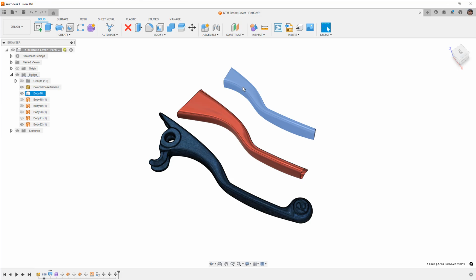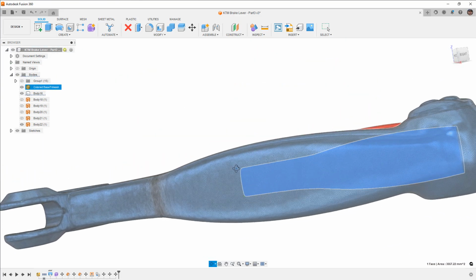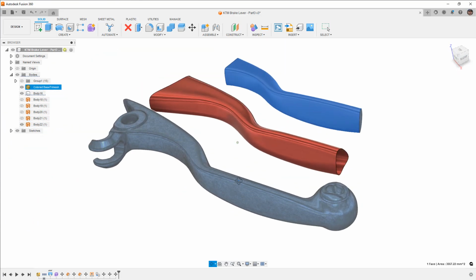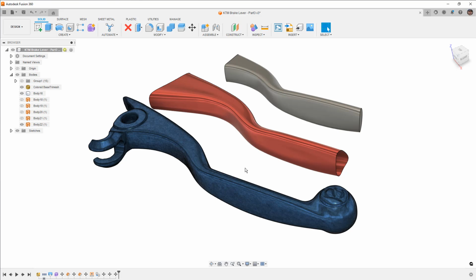Now, when we looked at the mesh section sketches, just for a little bit of background, if you haven't watched the first two videos, the mesh section sketches were a great way to capture the mesh data specifically, but we did end up with a lot of basically unusable splines. The quality of the spline just wasn't great. If you're going to 3D print something or you're not looking at fabricating it at really high precision, it's probably fine. But the quality of the freeform surface was much better because there were only a handful of points snapping to the mesh, and we weren't trying to accurately represent the mesh with a spline.